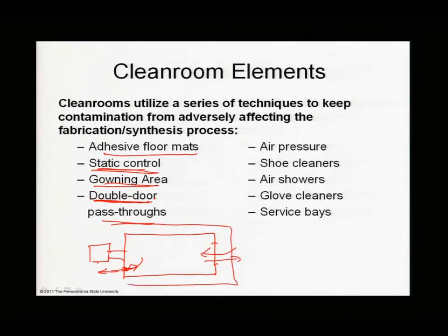And then of course you have to have a chase around, and then you have workstations that may be in the chase with just an interface region, or maybe in the clean room. It can be with a ballroom design, as you see here, or it can be made up of bays. Bay here, bay here, and you have all these different options. You have to control the air pressure. You have to worry about maybe shoe cleaners out here.